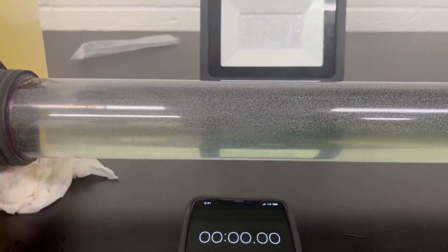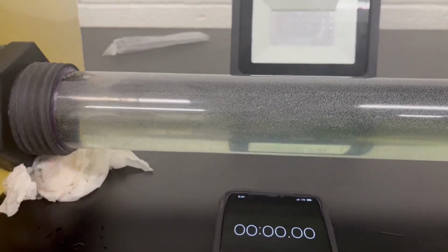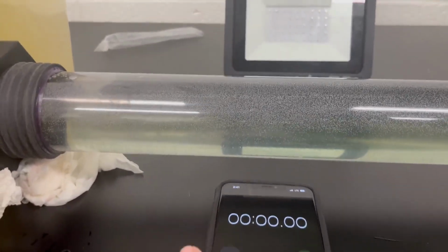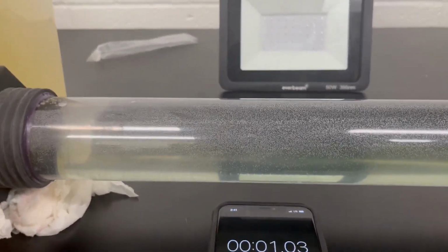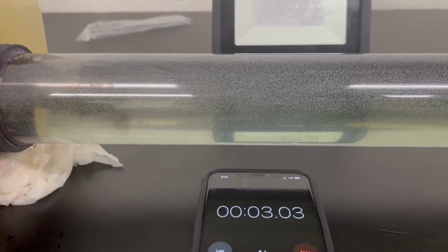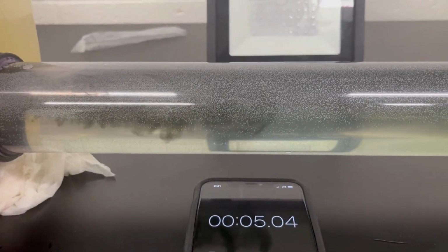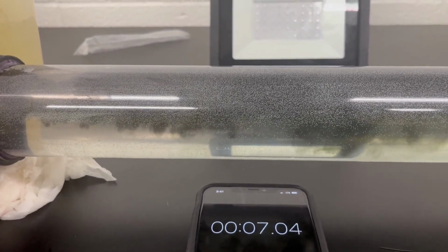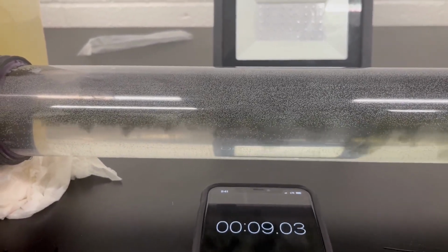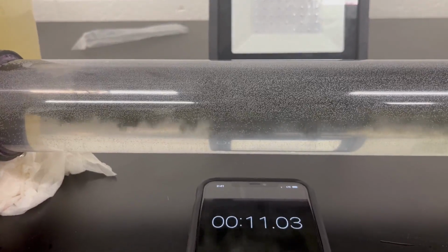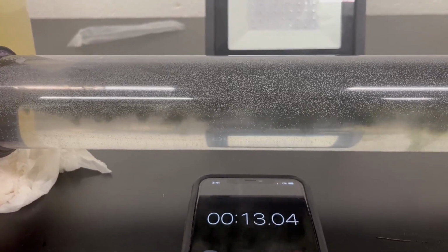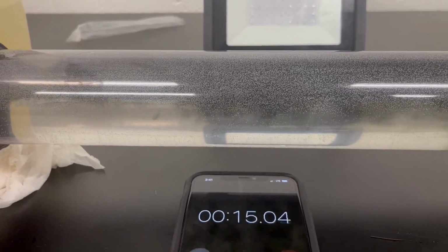With that, we can get into how the experiment was conducted and show a little footage of Reynolds number in action. We begin by looking at the viewing section. This is where our dye is going to come out, and we start a timer with the ball valve fully open because this is a turbulent trial. As you can see, the dye is mixing and cutting because the velocity in the pipe is very high, so it means we have a high Reynolds number.